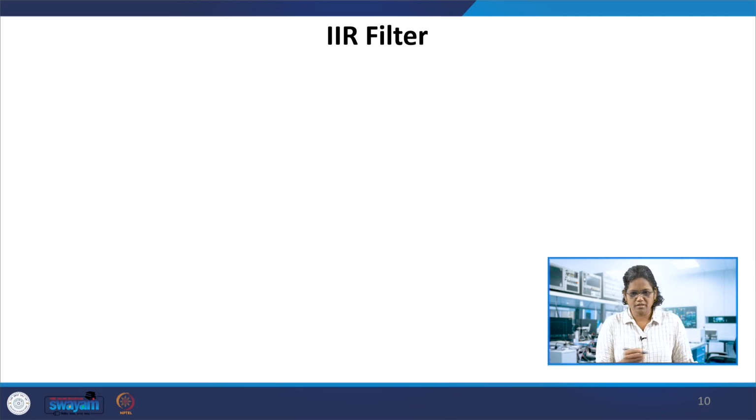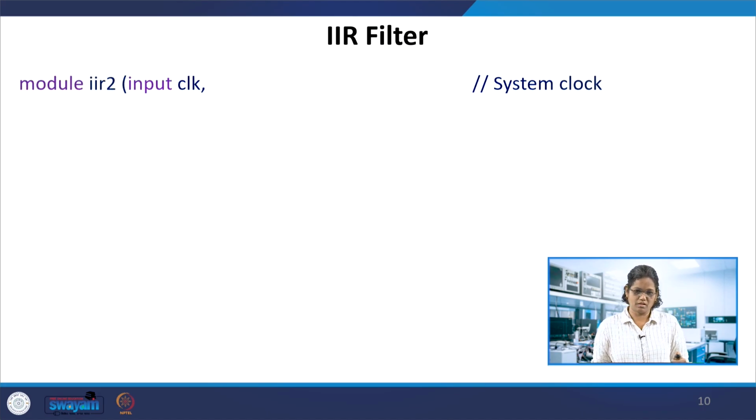But how do we write this in one simple line? If we have the delay in the equation of only y of n minus 1, there is one line after giving the x input, and y of n can be obtained. But if we have more delays in the feedforward and feedback paths as well, then you have to store the previous values, y of n minus 1, and then use them in the next line. So we'll see some examples on that.